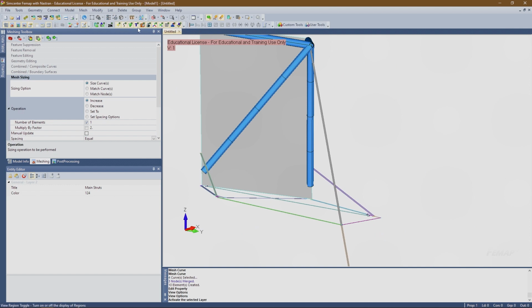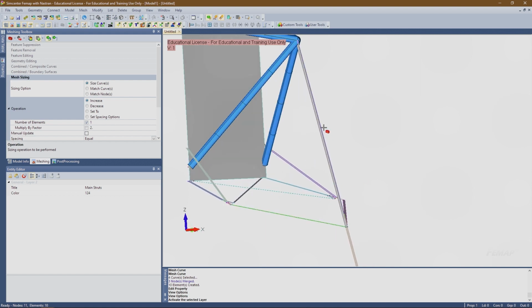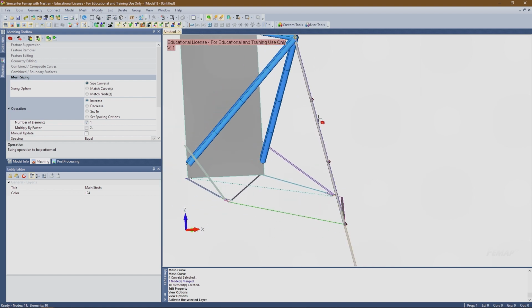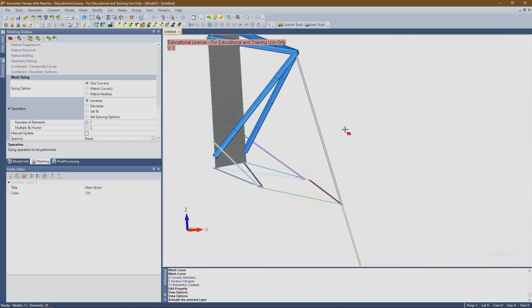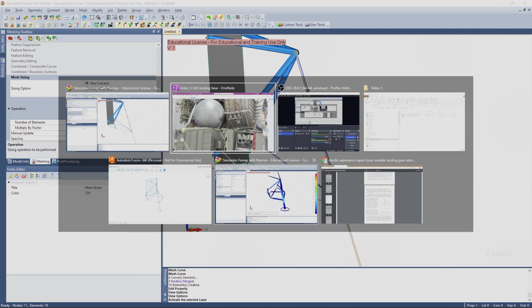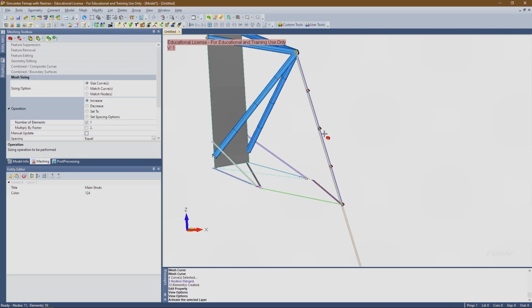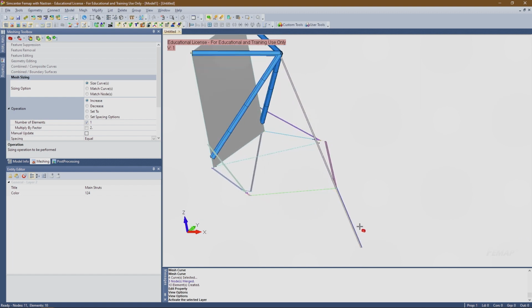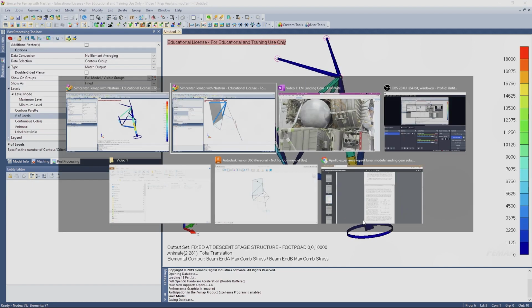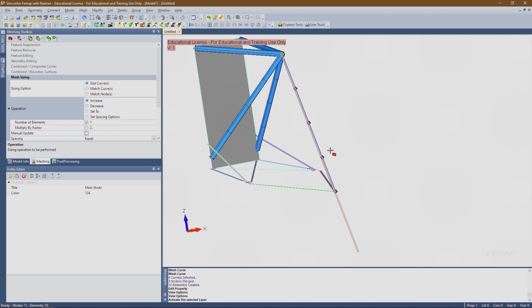If you'll remember, these are 2 separate lines. So I'm going to hit this guy and mesh this. So now we have 2 elements, 3 elements, 4 elements. I think that should probably be okay. Is that what I went with in the other model? 1, 2, 3, 4. Yep. Okay. So that's good. And then we want to do the same thing down here. I don't think we need 4 for that. I think probably just 2 is going to be okay. We can do 3 though. And then just so it maintains the same element size, we'll do 5.